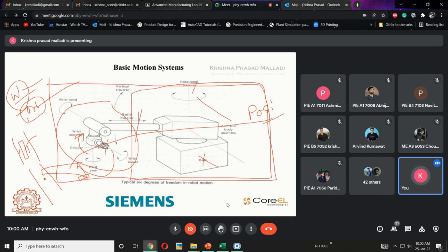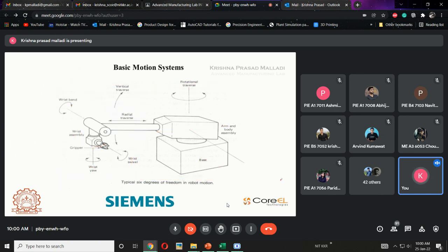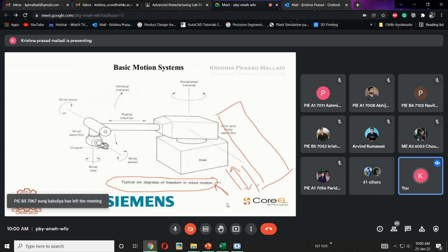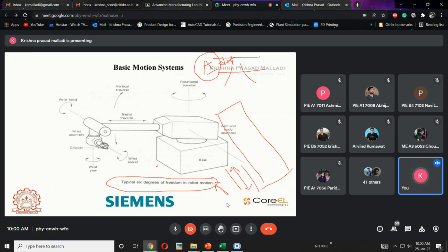So typically every robot will be having 6 degrees of freedom. But in the video they have shown, if there is an additional axis, I mean if there is a linear movement or an additional movement, then that is called an additional axis that does not come with this 6. This 6 motion comes with the robot itself. Then the additional one, which means the robot needs to move from one direction to another on the conveyor rail, or if it is overhanging, then there will be some other degrees of freedom, which will be called an additional DOF. Okay, that is called an additional. Whereas the self degrees of freedom is nothing but the robot movement like this: base, shoulder and elbow. These three will be used for this one. See here, this is called a rotation.